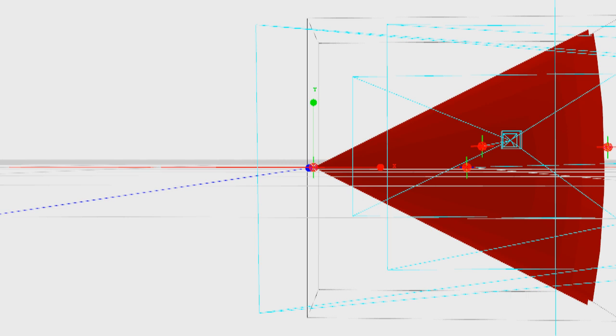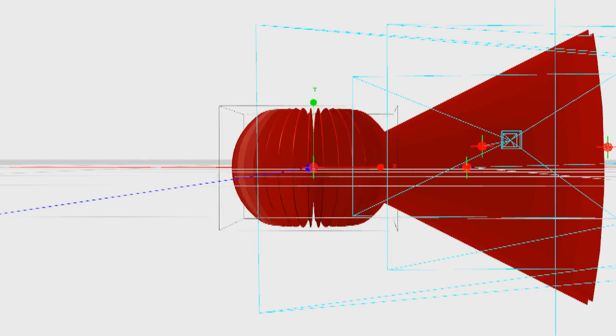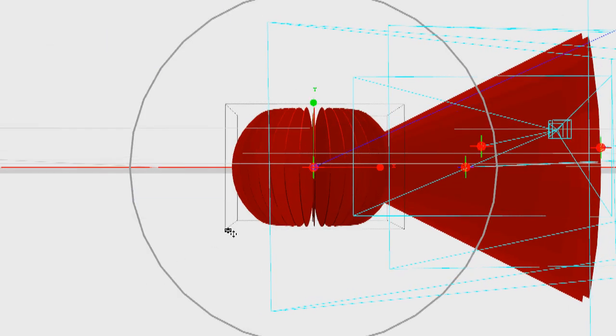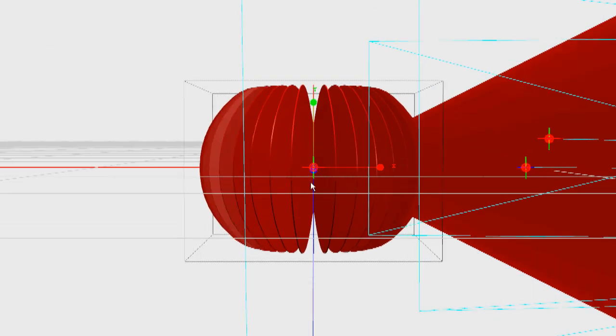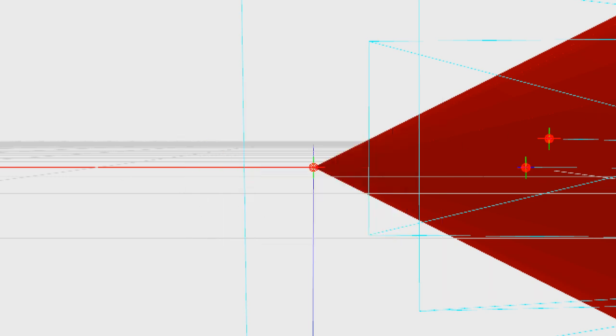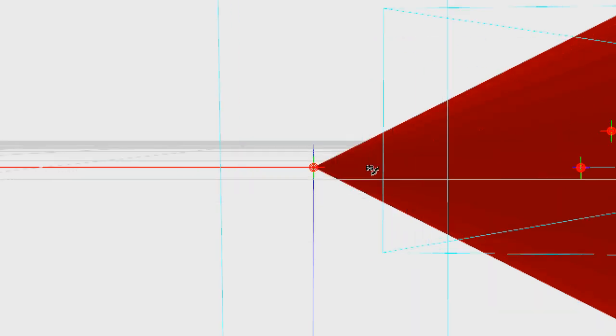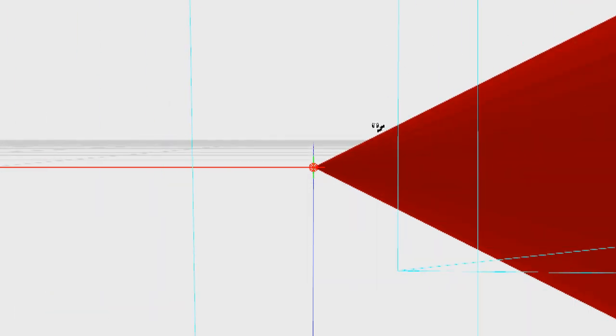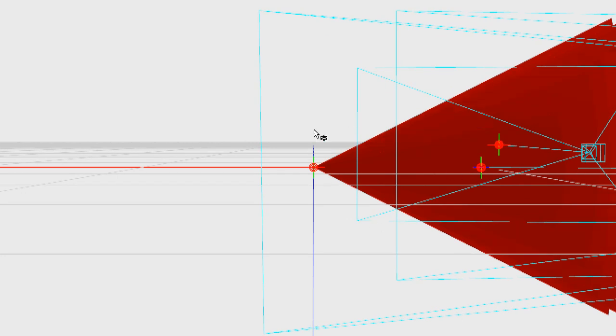Yeah, so if we compare that to the rubber ducky antenna on the ground, this is our central point here. So we're forward facing. There's nothing around the back for the diversity antenna. So there's no good flying behind it or above it. So one of the downsides is that it's a much narrower field of view, meaning we need to make sure the antenna is pointing very specifically at the aircraft.